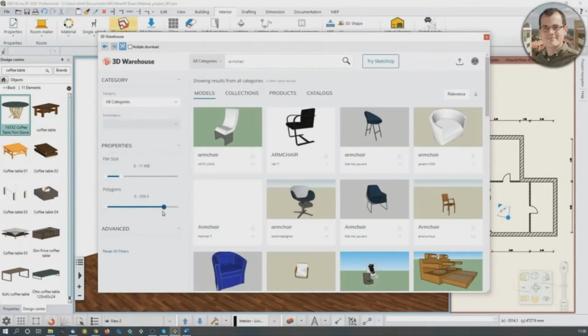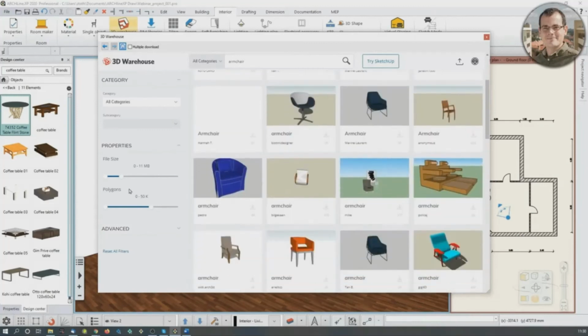So the general rule of thumb is to keep this under 50,000 surfaces, because if it's over, then you are going to have way too many surfaces, which would be impossibly long and difficult to render. If you have something in your model which is like a focal point of your design, you could go above this, of course, but if you're just looking for chairs and nominal things, then this is the way to go.